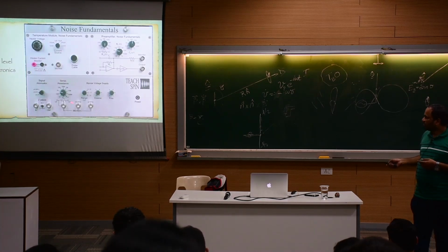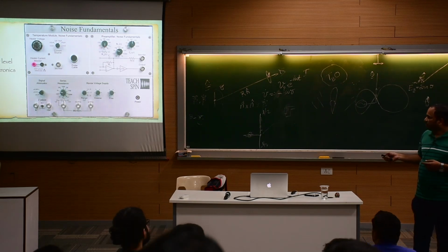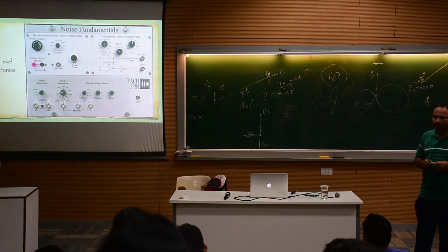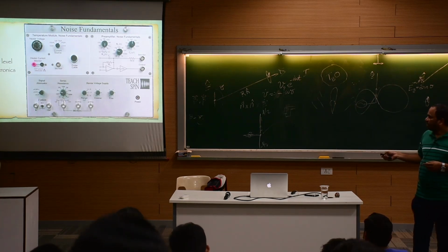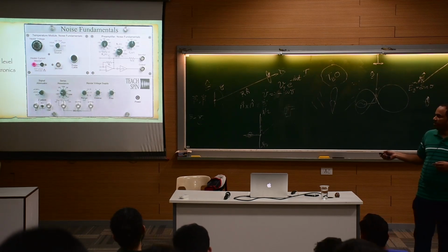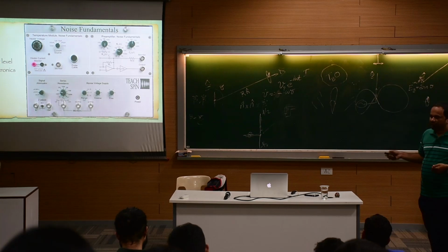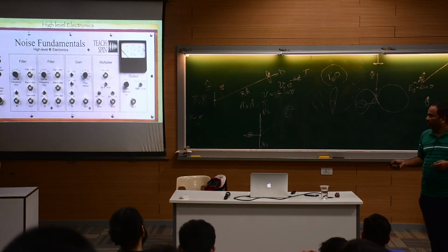So this is the low level electronics. Here you can see there is R_E. This is the input resistance which we can change. It starts from 1 ohm and can go up to 1 mega ohm. Then we have R_F, and here is the primary amplifier which has a gain of 6, and this is the secondary amplifier which has a gain of 100. So the total gain will be 600, and from here we take the output and connect it to the input of the high level electronics.